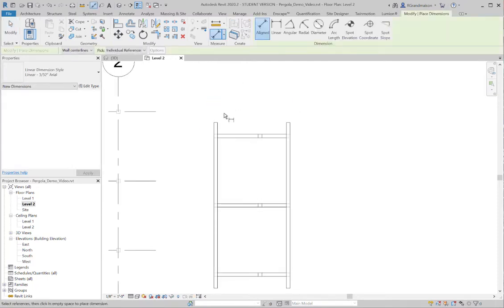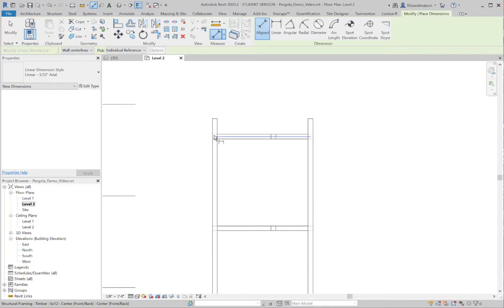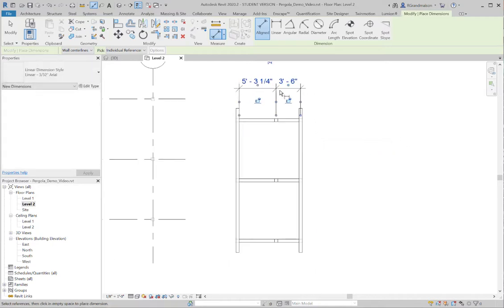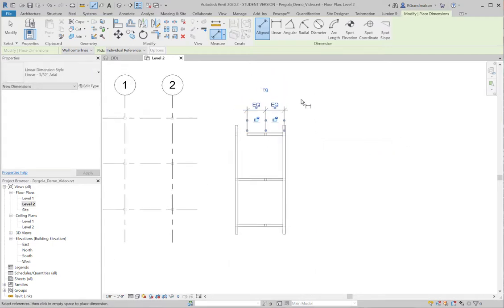Now, if you try to use the beams to do this trick, you're going to end up having problems. So you'll want to actually center it and align it based on the post that you have below here, this originally placed column. So what I'm going to do is tab select and find the center of that. Once I can see it, I'll click, find the center of this one, click, find the center of this one down here by tabbing, click, move upwards, and now I will equalize those posts.